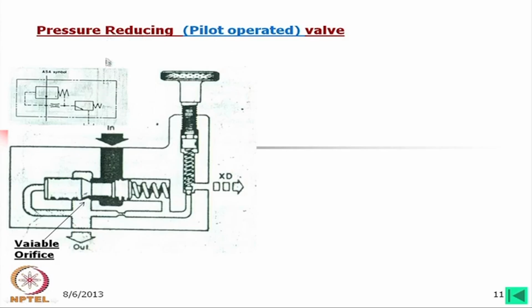That means, in this line there is a pressure relief valve. You will find whatever flow is not being utilized is going through this relief valve. This means that we can regulate this pressure, but in this side the pressure will remain the set pressure of the main system relief valve, that you should remember.